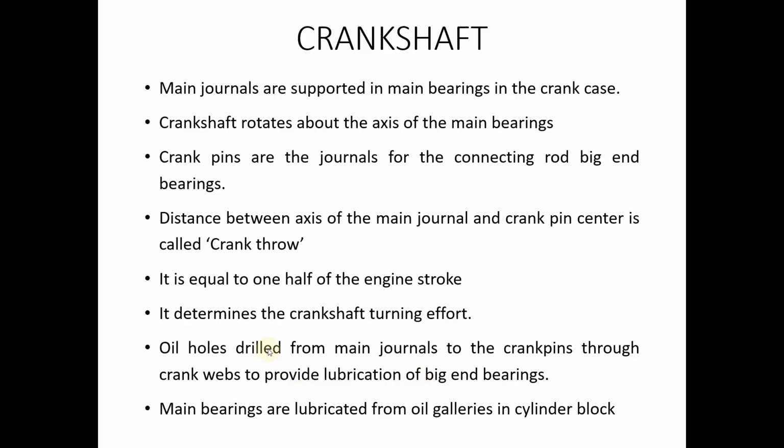And we also saw that the function of the holes drilled in the main journals is to supply oil to provide lubrication. And main bearings are lubricated from oil galleries. Oil galleries simply means they are small areas where the oil is stored once we pour in the engine oil. So in the cylinder block there are certain areas known as oil galleries which supply oil, or where the oil is contained.